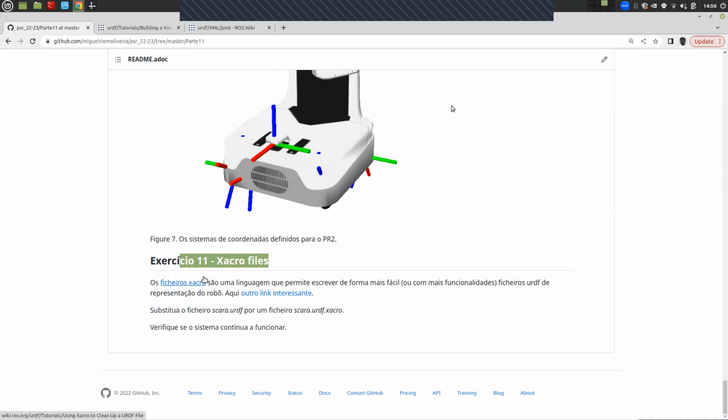Because, for example, you've seen in this URDF file that I was doing something like the length X of my cylinder. So I define a cylinder, then I define my length 1.6. And then when I go to the visual, because I know that the length of the box is 1.6, I have to do the origin and subtract in X half of 1.6. So here I put 0.8. This is really not very good for a programmer to work on. When this is very large, it's easy for you to get lost in so much detail. So that's one of the big problems of the URDF. You can't have any kind of variables or math.